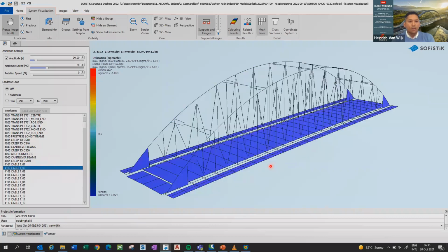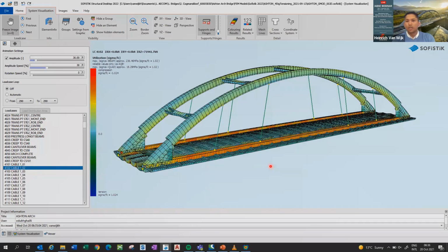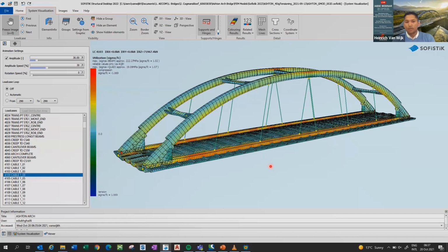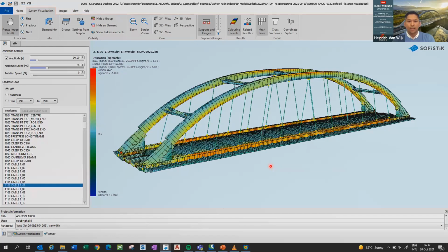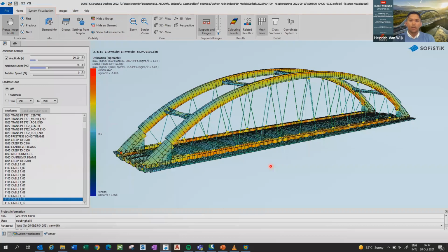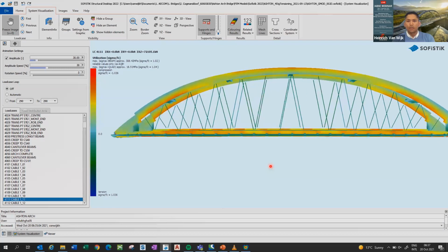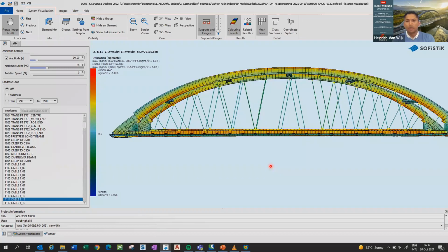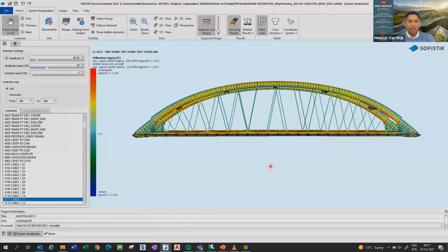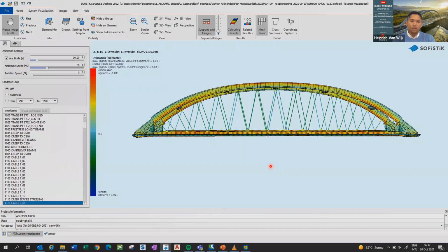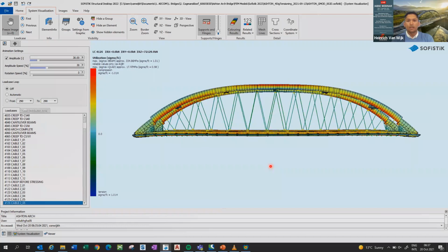And then the tensioning of the first stage of stay cables or hanger cables. And we actually broke up the tensioning of the hangers into two stages, where the first stage is essentially to pick up most of the dead load of the structure. And then you could say that the second stage was to almost optimize the stress distribution in the structure.